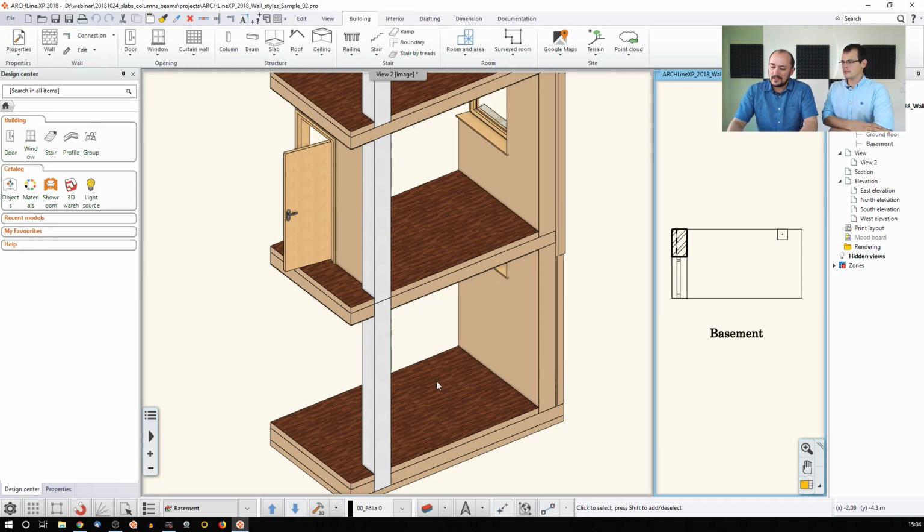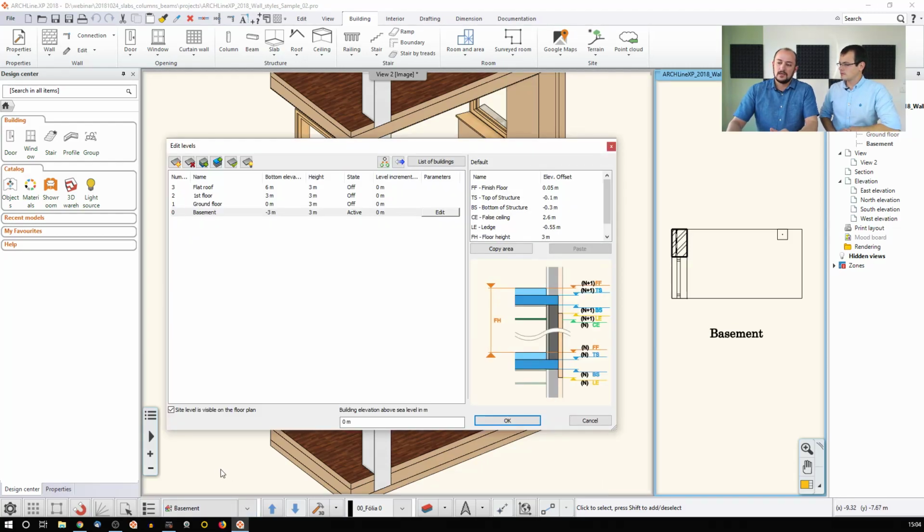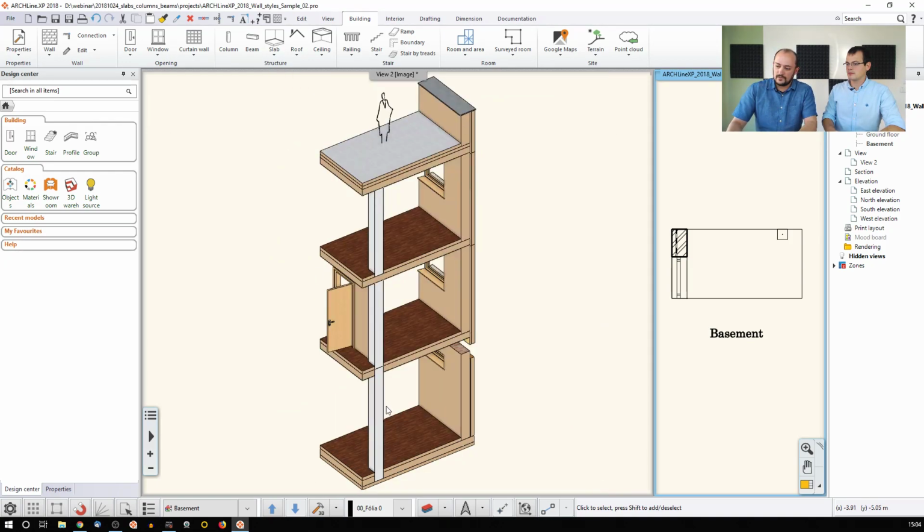On the basement level, we now have a certain floor to floor height. That's actually the floor height in ARCHLine. So if I'm about to change that, for example, to elevate it and say this should be larger by 45 centimeters, and I say okay, update that, the software shows this difference.